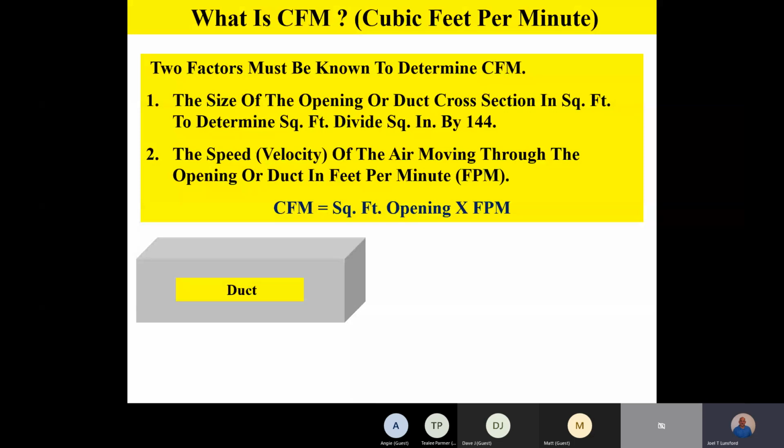So that duct right there, let's say this is the main trunk on a unit, and let's say it's a 4-ton unit. That would be sufficient for a 4-ton unit, that size duct, 1625 CFM. Now at this time, I'd like everybody please to write this down or make a note. We always want to size our main trunk. We always want to size our ductwork, our entire duct system.